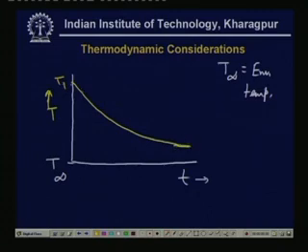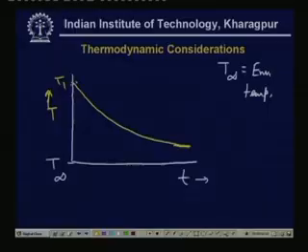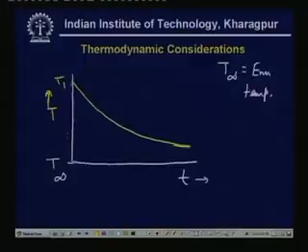Now, we see that once we give a heat input, that is once a braking operation is done, then the temperature goes high to a limit T1 and it drops down slowly depending upon various factors like U, A, M and Cp, and also the difference between the initial temperature of the body and the environmental temperature. Now, suppose after time T1 we apply another braking.